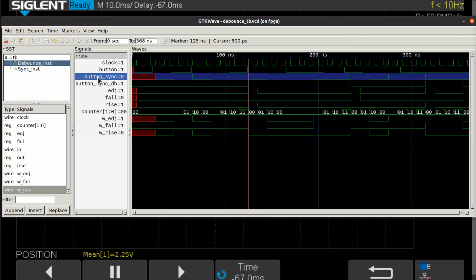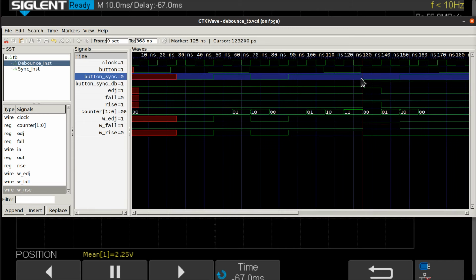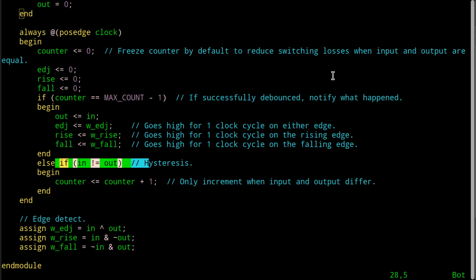If you lower your input signal here, like over here, this will still output this because the logic doesn't care that it has gone away at this particular point in time. It has been high long enough. This thing got to 3, and we have a rising edge on our clock because it checks the value of the count before it cares about the input. That's why we got an else in here. And we don't get here when this is true, is my point. It won't be until the next time the clock ticks that it'll want to check down here again.